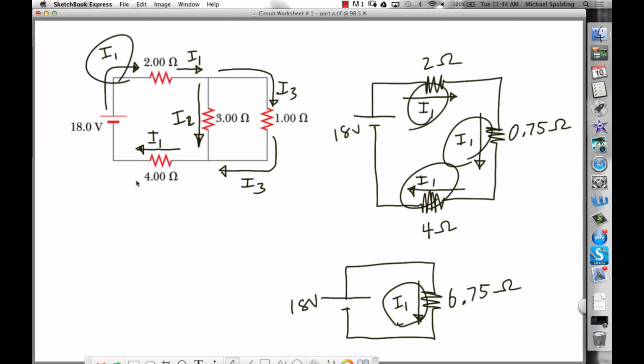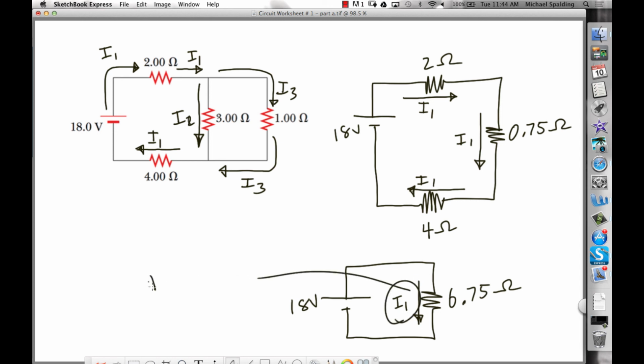So in general, the way you do a circuit problem, here's how you do it. Ready? It's the biggest thing I can show you. You take the circuit, you break it down to one resistor. Simplify, simplify, simplify, and then show all the pictures along the way. Once you've simplified it, then you work your way back up. Like what I would do here, first find what I1 is. What's I1 going to be?